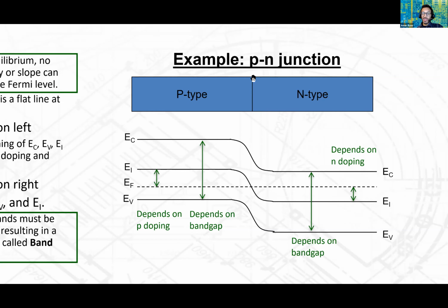It starts to look more like an intrinsic semiconductor. In an intrinsic semiconductor, the Fermi level is right at the intrinsic level. So you see here how EF and EI cross together. This is happening at the interface because right at the interface, you essentially have an intrinsic-type semiconductor.